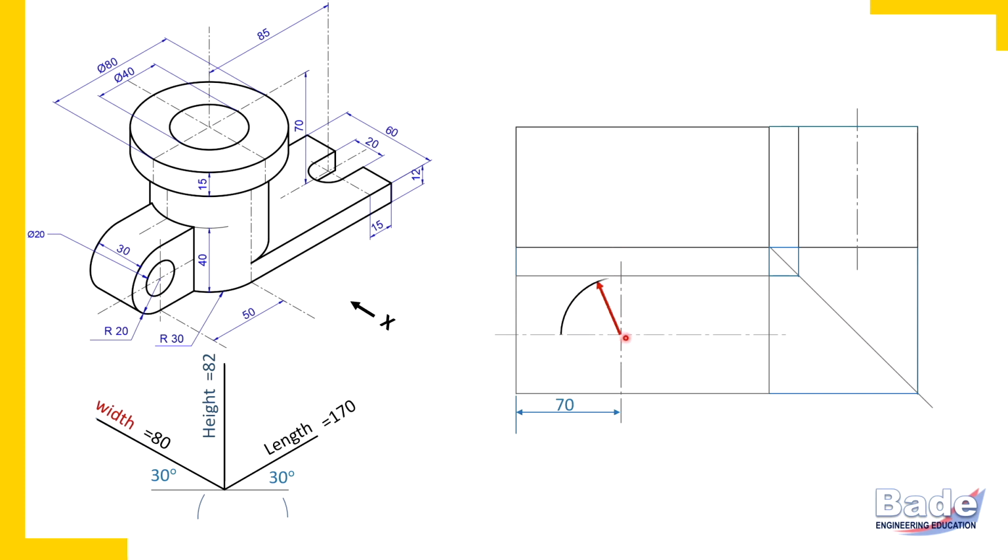Now draw a circle of radius 40, that is diameter 80, and a circular hole. So two concentric circles. The outer circle is the disc itself and the inner circle is the corresponding hole. This circle is the edge of the hole, the opening of the hole that is visible in the top view.